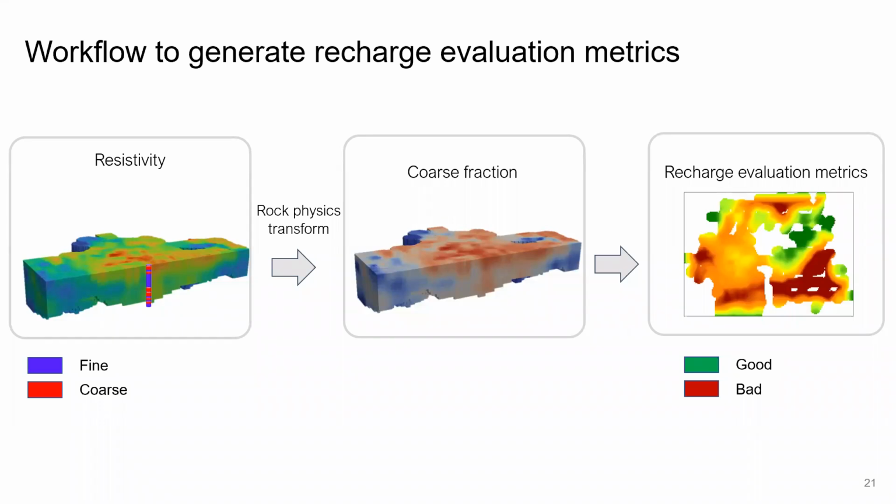And so that's kind of what I have shown, what we can get from airborne EM or EM imaging data is the resistivity. But to be useful for recharge site location, there are a couple other steps that we need to introduce, because resistivity itself is somewhat limited because there's an uncertainty to define what is the coarse grain unit or the clay unit, or to define the sediment type or other types of rocks.